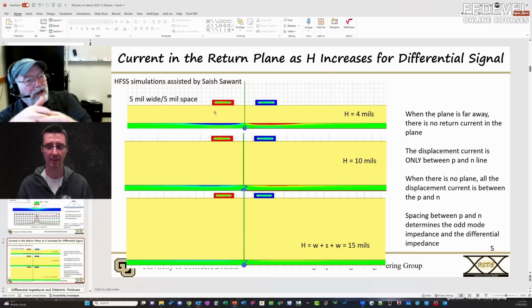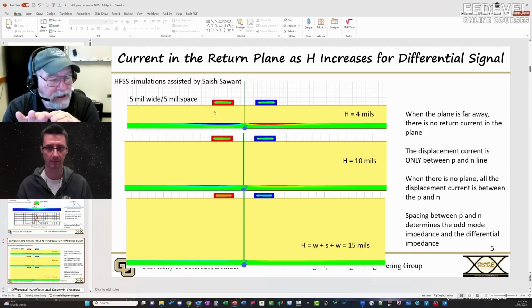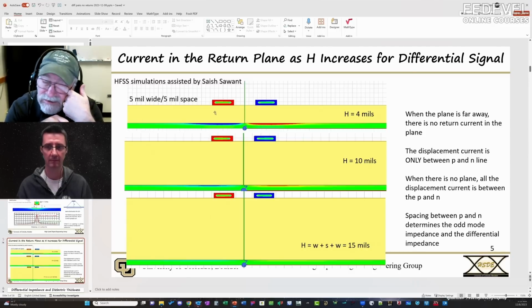And this way you can control the single-ended impedance of the individual track. Well, yeah, but I'm talking about the DC resistance, the actual conductor resistance, because that plays a role with conductor loss. And if I care about interconnect density, then tightly coupled is better. If I care about loss in all of its forms, then I want to balance. I want to not use the tightest coupling because that means the narrowest line, and that means higher resistive loss.